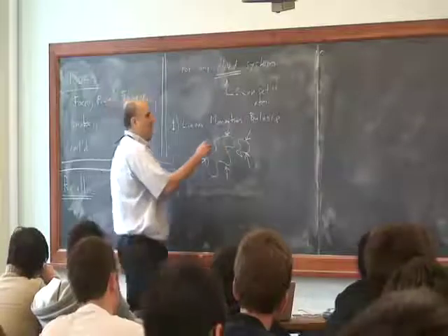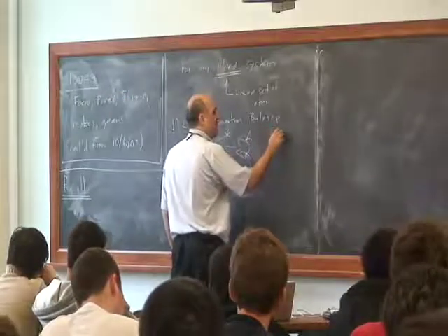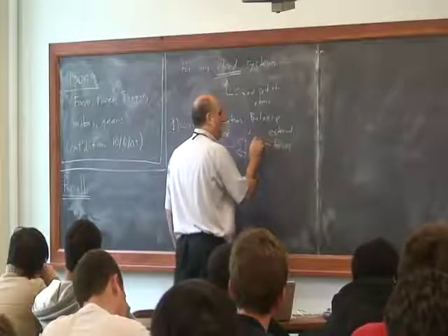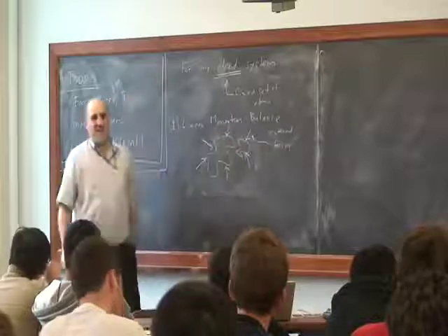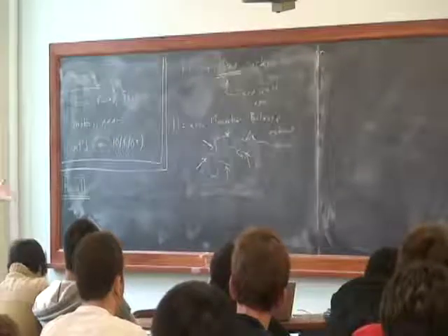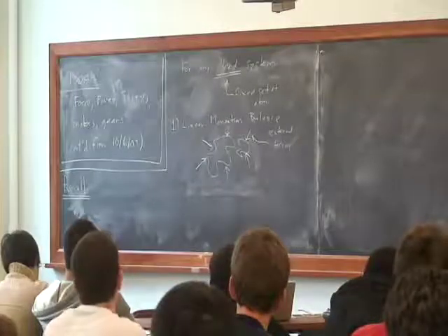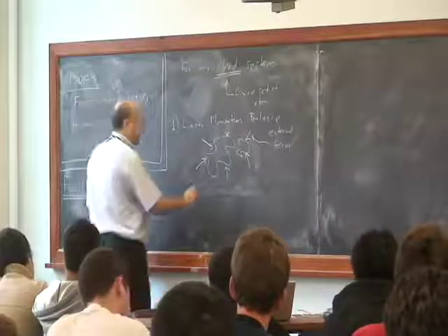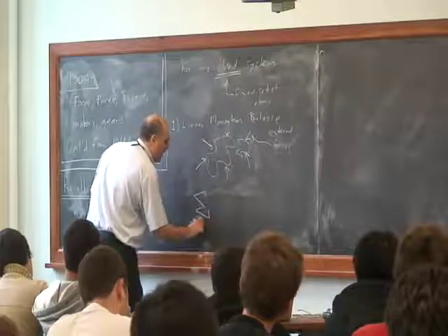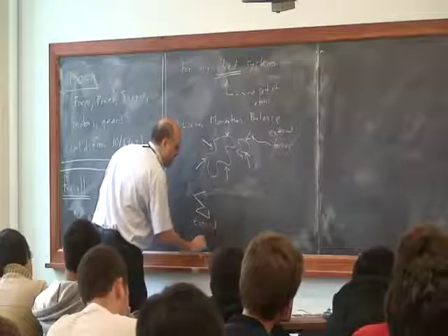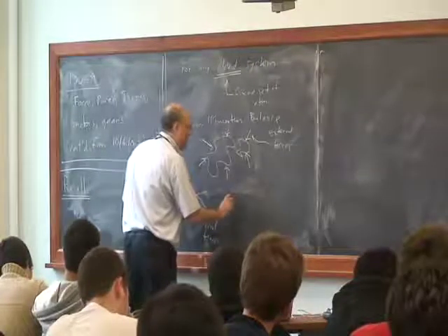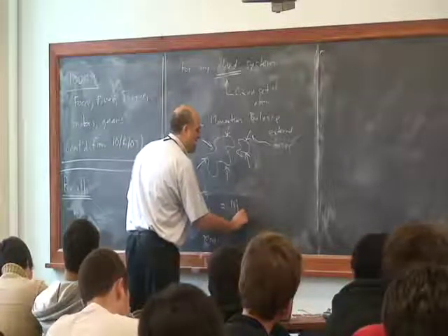In this free body diagram, you show the external forces, and it's very easy to make the mistake to try to include internal forces, but they don't show in this model of a closed system. You look in a closed system at what the influence of the outside world is on the system, and if you take all these external forces and you add them up, so this is a sum over all external forces, and this system, however complicated it is, still satisfies this equation.